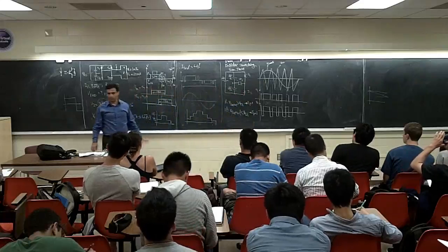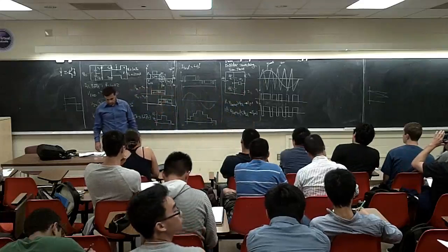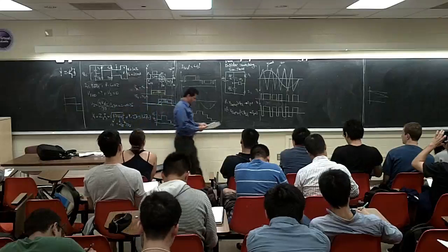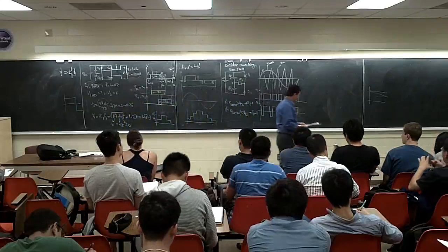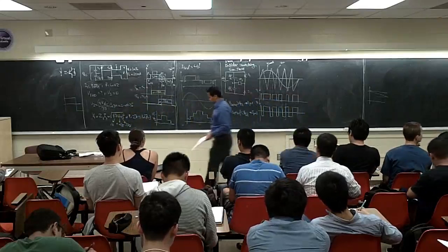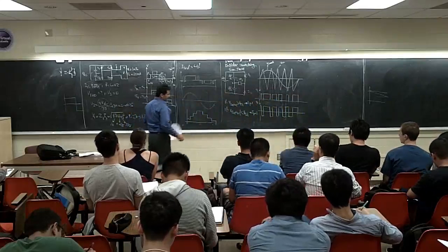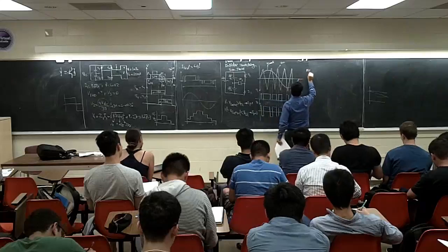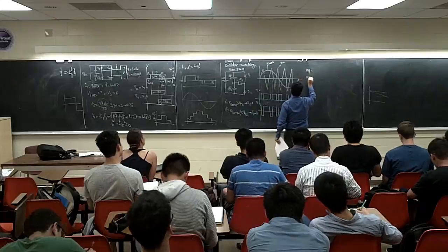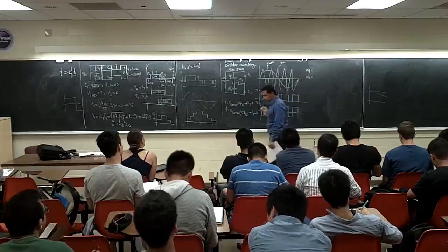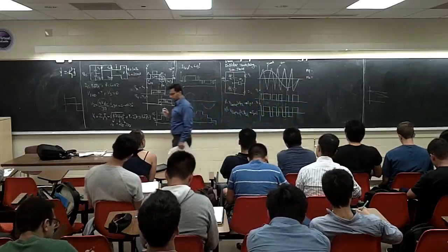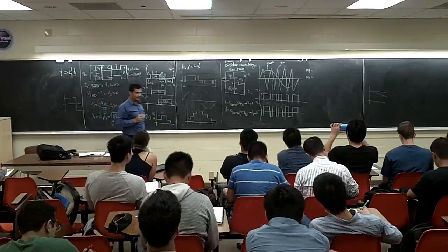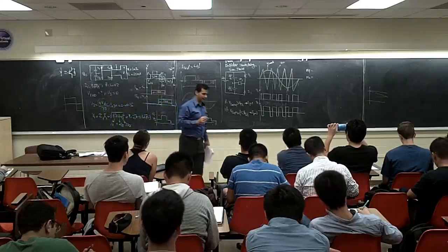Now, what is the bipolar? This is for the half bridge. But what is the bipolar PWM? When you say bipolar switching, two things I need to introduce here before we go. There are two parameters we need to define, MF and MA. MF, they call it frequency modulation, and MA, they call it modulation index.